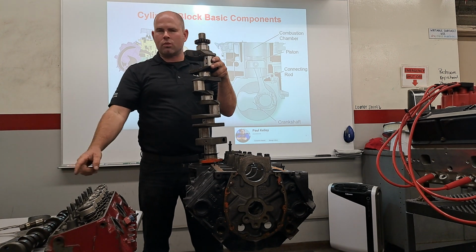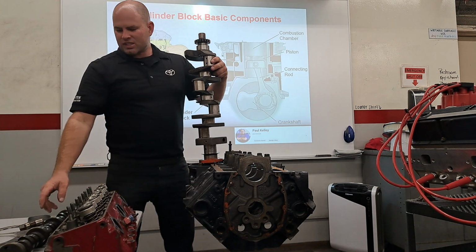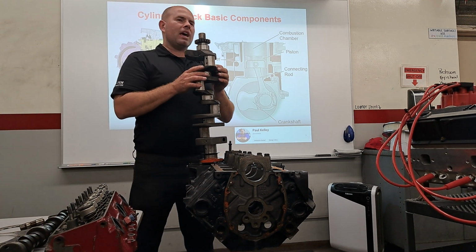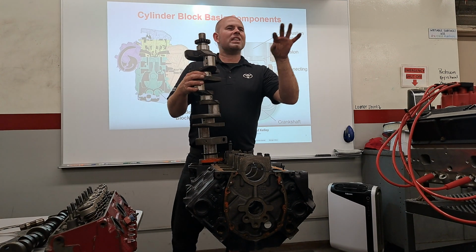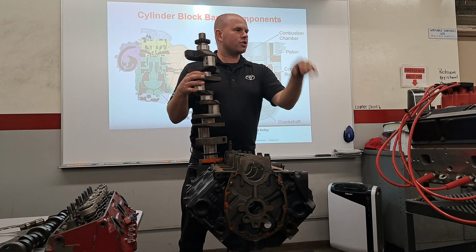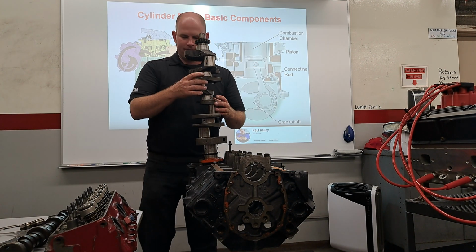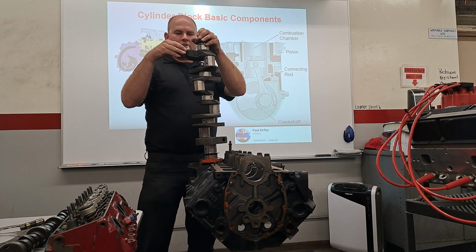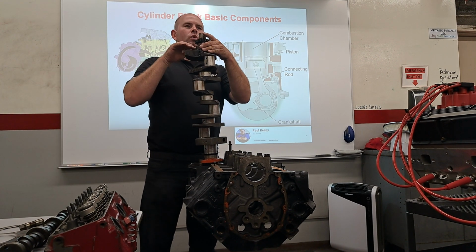But let's just say it goes even further than that. Let's just say I ship the car. And the customer's like, oh, there's a light on. It's a genie light. I guess I'm going to get my 3 wishes later. And they just drive it. They just keep on driving it. Well, what can happen is there can be so much friction here that the main bearing will seize to the crankshaft, and then guess what the bearing will do?